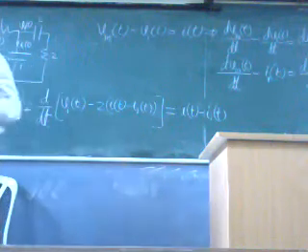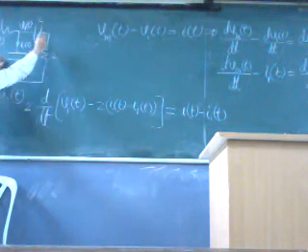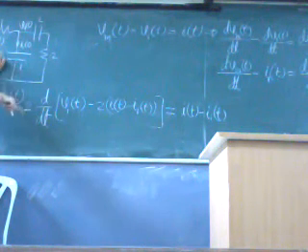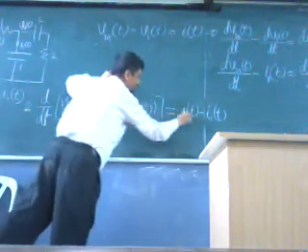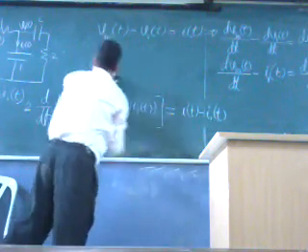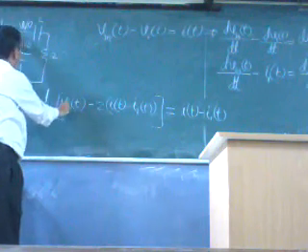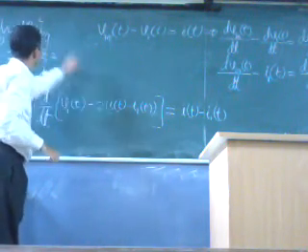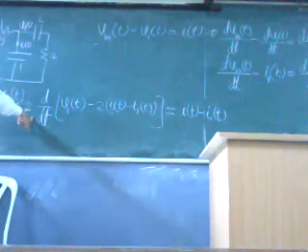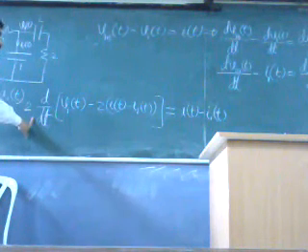We have tried to write a bigger equation. Current through a capacitor is equal to C into dV/dt, where V is the voltage across it. So the current through the capacitor is I(t) minus I1(t). The voltage across it is V1(t) minus this voltage. This voltage is 2 into this, and its differential. So this is a big equation we have got.